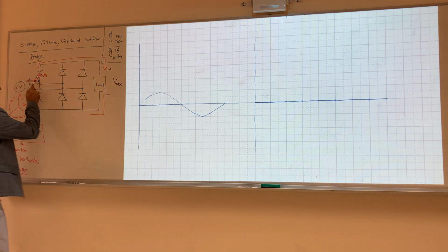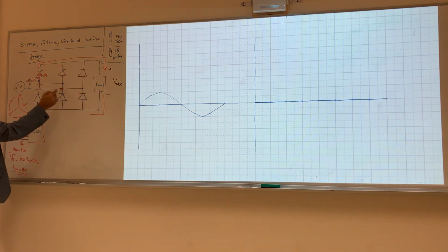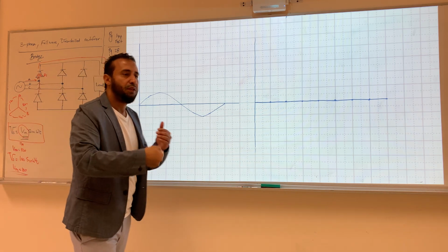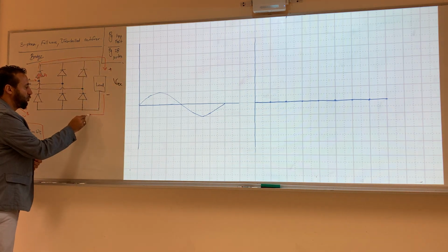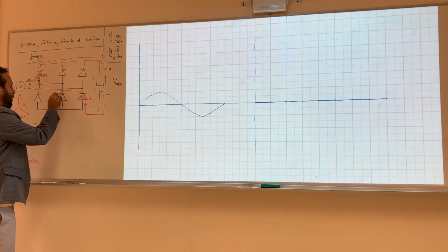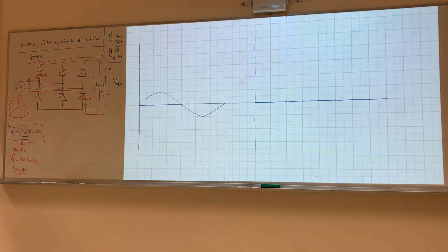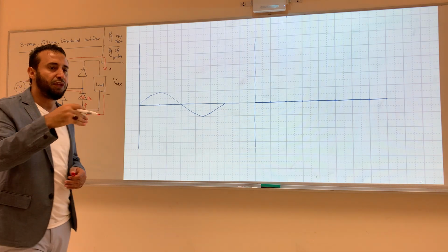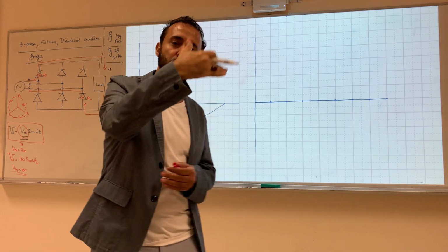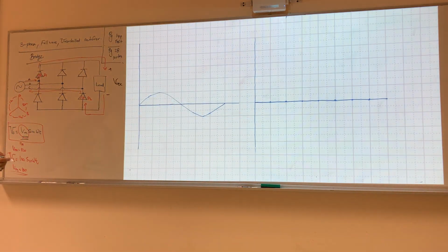If it starts from A, it has to close by C, because they go by sequence, A, then B, then C. So this one here is diode number 2 by sequence, and now I close the circuit. If you start with A, then it closes with C. If you start with B, it's not closing with C, it's closing with A. It skips 1.